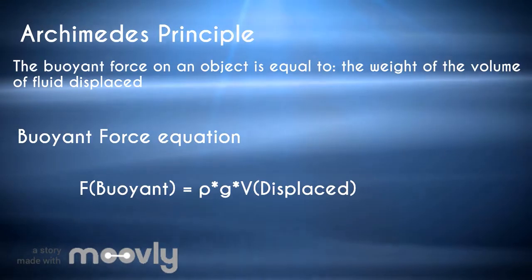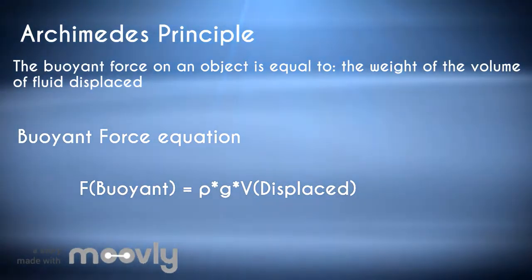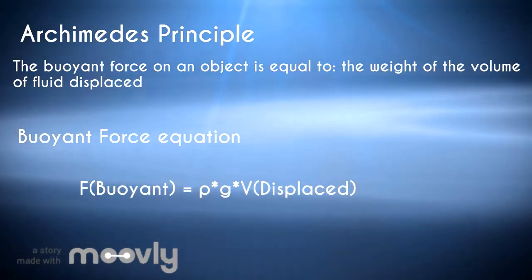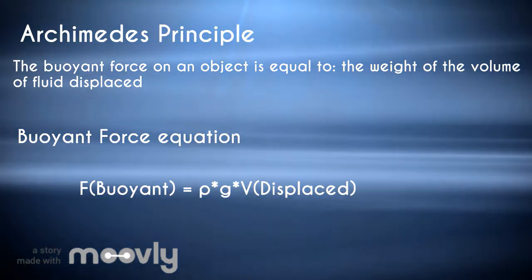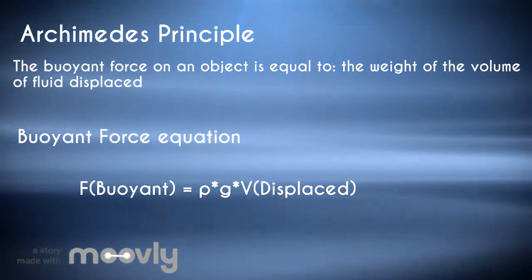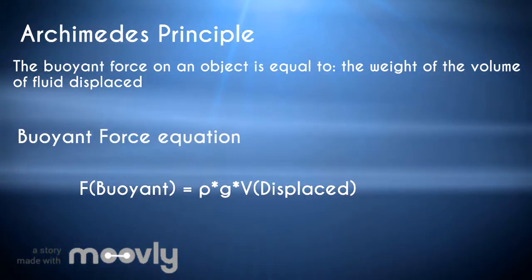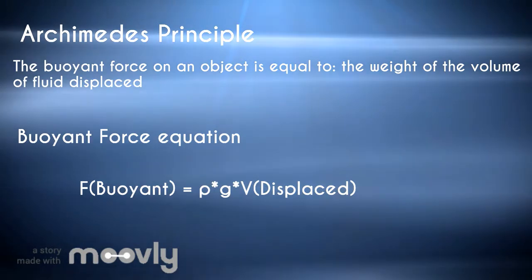In a realistic non-simplified version of this problem, we would need to do the integrals to calculate the exact center of mass resulting from the diver's irregular equipment mass distribution. We would also need to change the equipment placement to keep center of mass and center of buoyancy coincident.